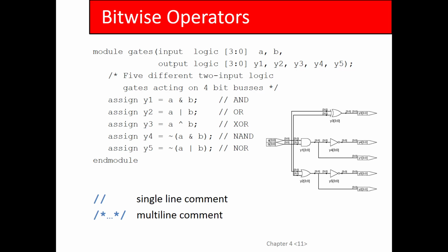So anyway, notice also that that comes before the names of the variables instead of after, like in Java, in C, in MATLAB, Python. Well, MATLAB, you don't have to declare variables. You guys with me? Okay, so what does this mean? It means I have two 4-bit inputs, and I have 1, 2, 3, 4, 5 4-bit outputs. You might say, wait a second, what do you mean by two? You only specify the size once. Yeah, because this size is applied to everything that comes after it. This is a shorthand where if you say input logic 3 down to 0, that applies to the A and the B. You guys with me?